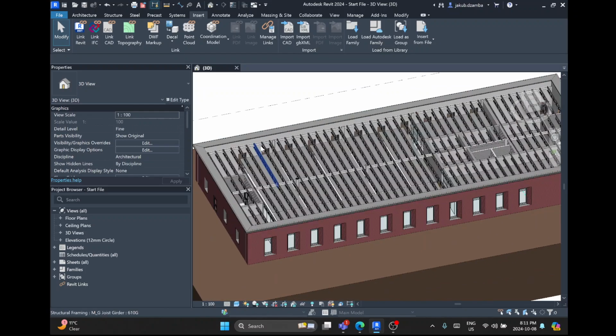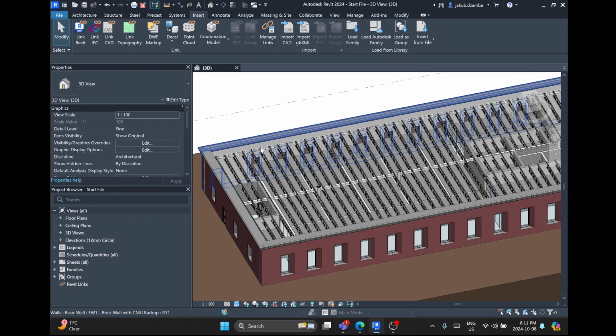So the big idea here is that now that we have a 300 millimeter concrete block on the inside, it's extremely structural in its capabilities. It also adds more thermal mass onto the inside of the building, so we could maybe use a radiant floor heating or some other type of heating method where the concrete soaks up a lot of heat. It's a bit more sustainable because then you can heat it, let's say at night when electricity is less used and there's a lot more of it available. So you draw less overall on the grid. Anyway, we can get into that later.